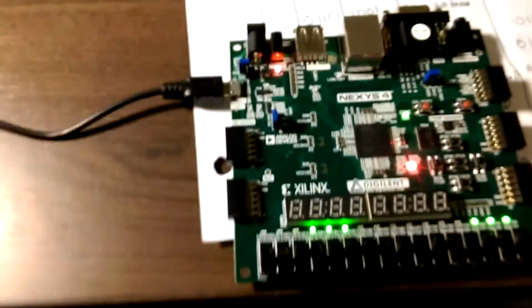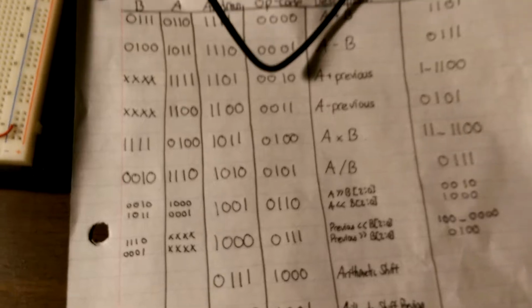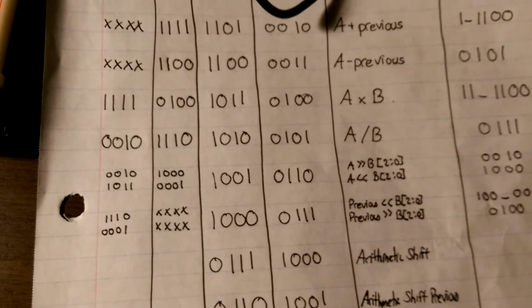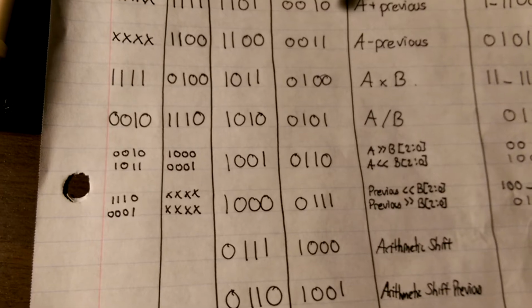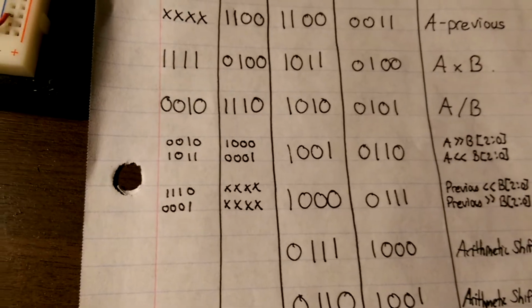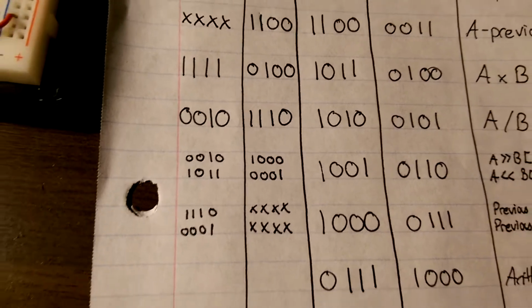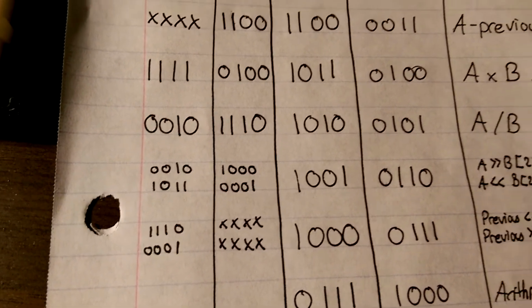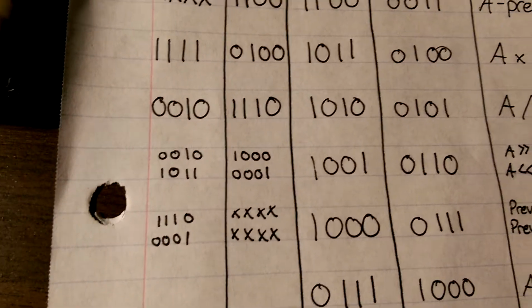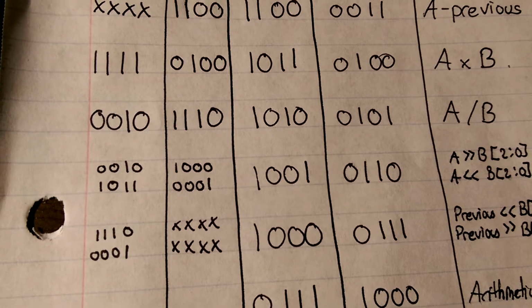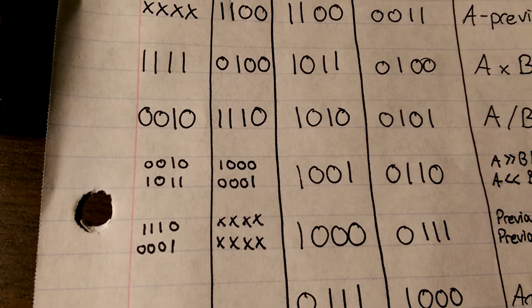Right, so now comes another fun part. So this is a dynamic ALU. This means that either of the inputs can be used as a secondary output. So in the case of shifting, I use this format. Opcode is going to be 0110, and depending on the input for B, for the most significant bit, you shift right with a 0, you shift left with a 1. And the last 3 bits of B are the quantity to shift.